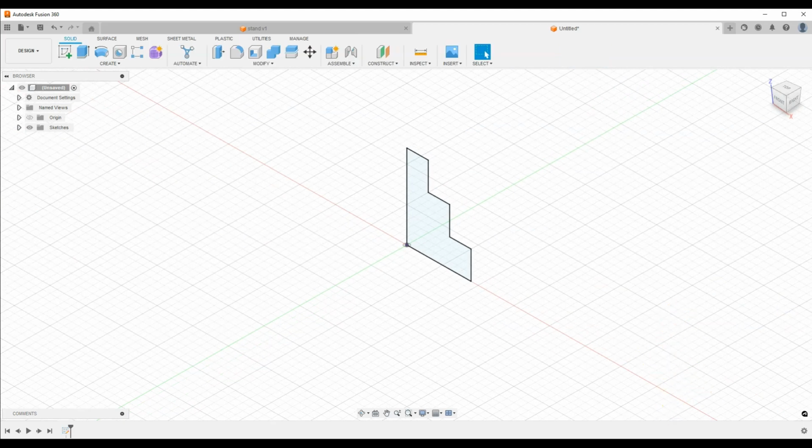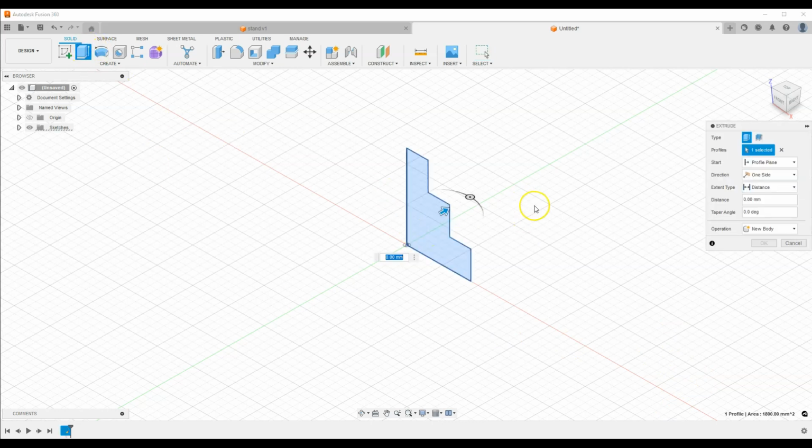will add an extrusion. Select the extrude operation, select the profile. Here in this case this profile has been selected by default. We only have one sketch, but if you ever need to select profiles, you can do it here. If something is wrong, you can click this button to deselect all profiles. This button is highlighted, the profile selection is active, so now we can select this profile, and this profile has already been selected, and on the basis of this profile we will add a sketch extrusion, so that on the basis of a 2D sketch we create a 3D solid.